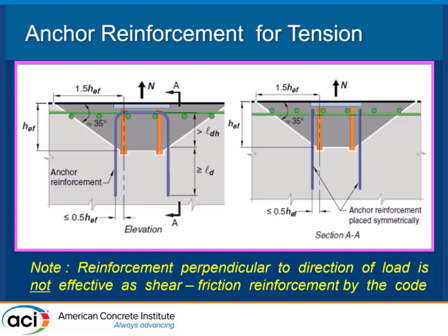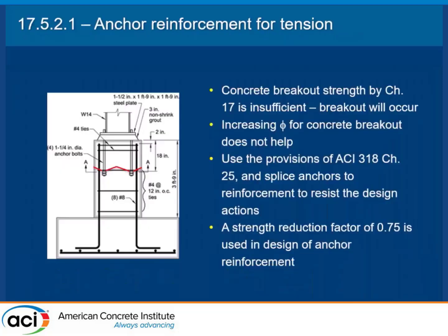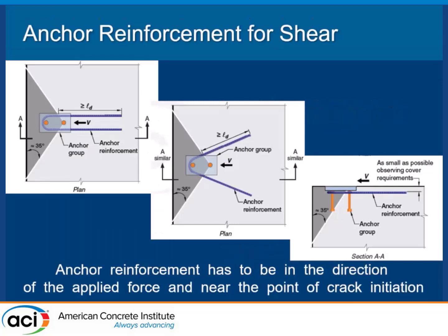However you do it, it almost makes a little more sense in shear, which we can go ahead to a little bit. We'll get into all this a little bit more, so don't worry about that. Same thing with shear, although shear is a little different. But the point I want to make here is, in shear, like on the edge of a slab or something, I typically have an edge bar, right? And then I'd probably have some mat steel coming over, and it would be hooking down, right? Well, I'm just going to have that there anyways. I'm putting this thing in here.